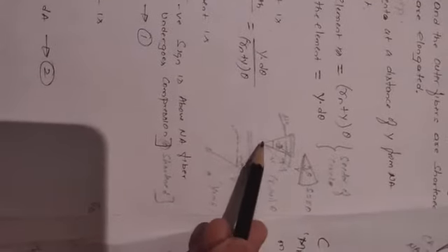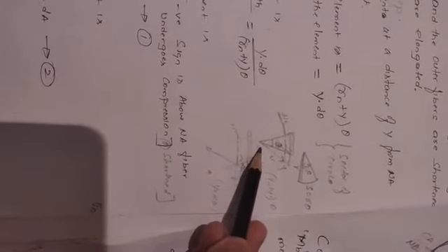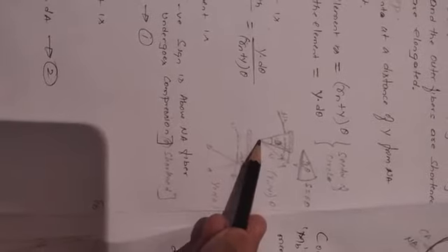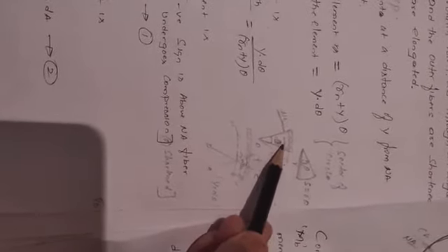Then let dA be the area of the element. Now what is the original length of the element? By taking the center of a circle, how do you determine the length? It is x equal to r into theta. The same formula holds good here. From the center of curvature to the neutral axis is Rn, and from the neutral axis to the small fiber element is y. Now what is the total radius here? Rn plus y, into theta. This is the original length of the element.